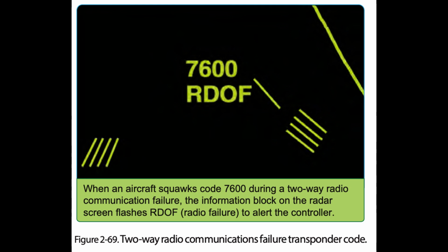Figure 2-69. If only the transmitter is inoperative, listen for ATC instructions on any operational receiver, including the navigation receivers. It is possible ATC may try to make contact with pilots over a VOR, VORTAC, NDB, or localizer frequency. In addition to monitoring NavAid receivers, attempt to re-establish communications by contacting ATC on a previously assigned frequency or calling an FSS. The primary objective of the regulations governing communication failures is to preclude extended IFR no-radio operations within the ATC system, since these operations may adversely affect other users of the airspace.